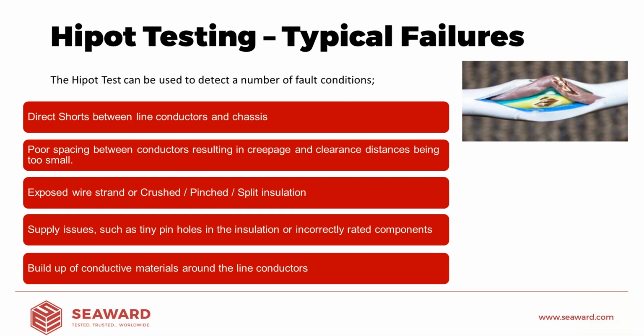And more on the maintenance side of things, if the product's being used in an environment where conductive materials are present, they could build up over time and potentially cause a shock hazard. So the Hipot test is designed to find all of these fault conditions. It's truly a versatile test within our arsenal.